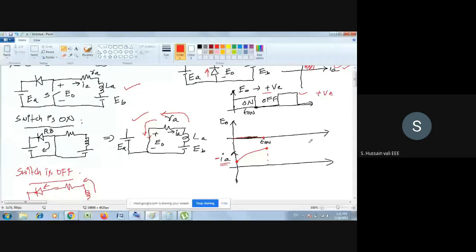But what will happen here is that the current gets reversed. Why does the current get reversed here? Because of back EMF. What is that back EMF actually? It is because of the rotation. Am I correct? The back EMF is because of the rotation. So now you are slowing down the motor. As you are slowing down the motor, the energy which is stored in the vehicle, the mechanical energy, will be converted and go back to the source. That is what will happen now.